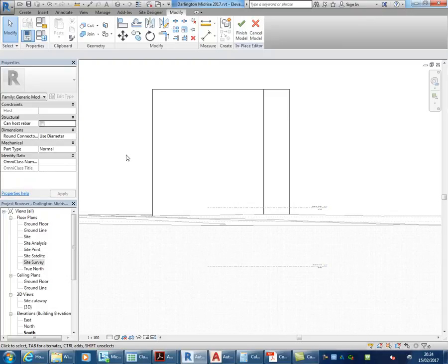Ordinarily, if I was placing these models on there, I would later just hide them. Does that not work? It does, but it's not the best way of working. It's just going to create more work for you that you shouldn't have to do. So what I think you should do is get your ground floor level, because it's already tied in with those site views and everything else.